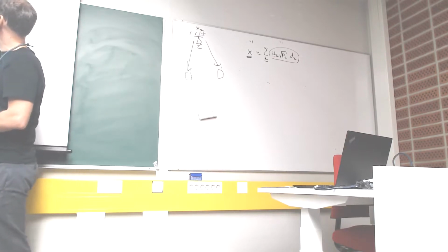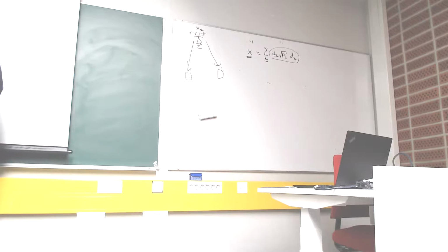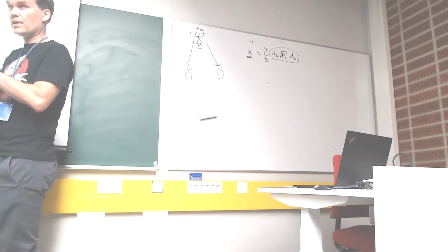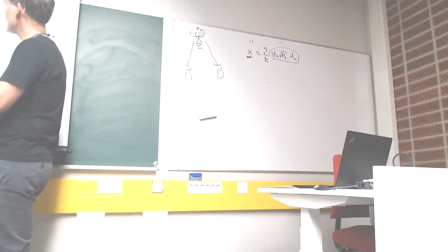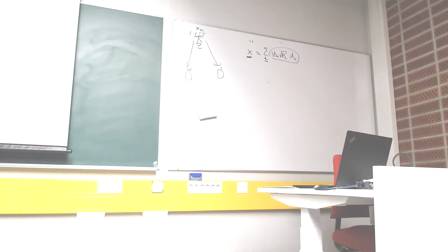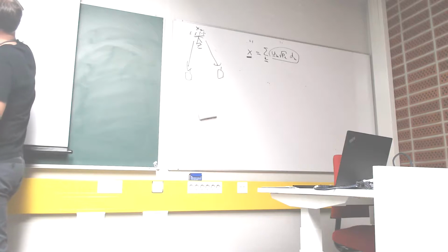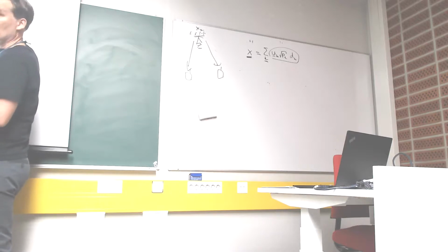On the other hand, if this is too high with respect to noise, there's something you can do better. So similar to MMSE in the uplink, you want to find precoders that simultaneously maximize this term, but push this interference term to more or less the same level as the noise.